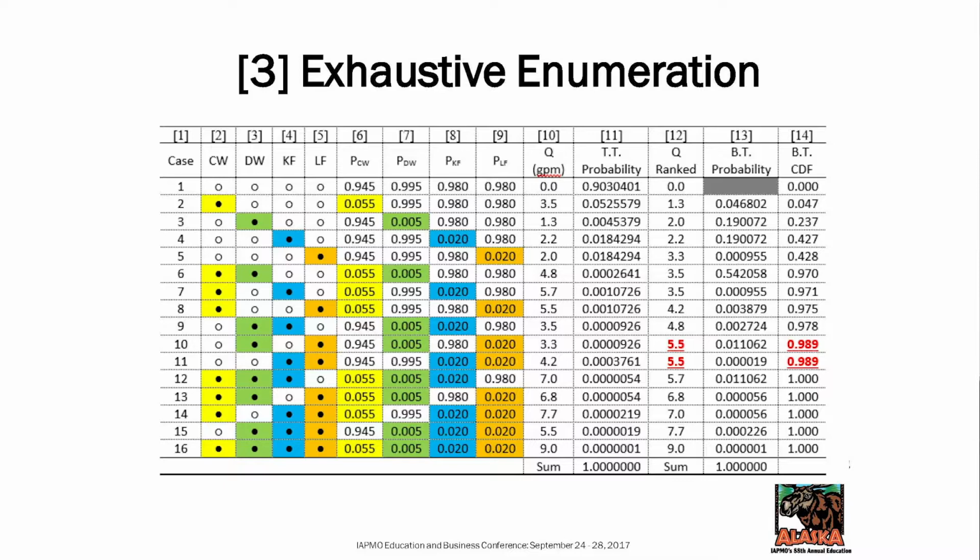So what this does is that whatever number of fixtures that you put in the calculator, it'll start ordering the fixtures based on all the possible number of combinations. So here we have 4 fixtures: clothes washers, dishwashers, kitchen faucets, lavatory faucets. There are 16 possible combinations. It's 2 to the nth power, whatever that number is.